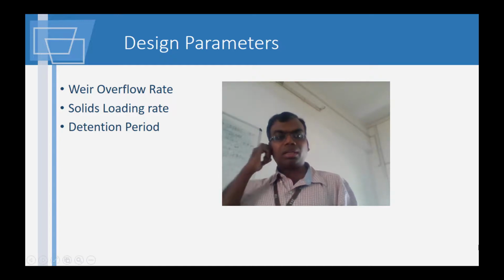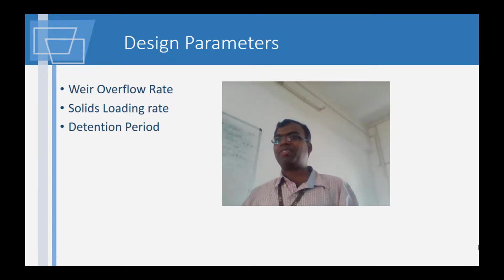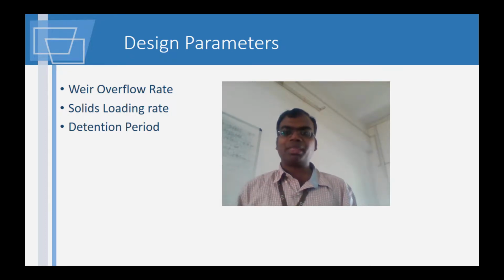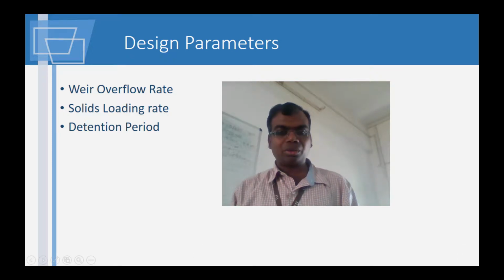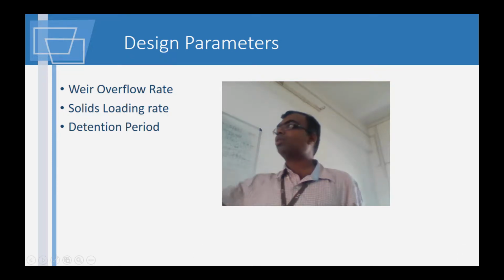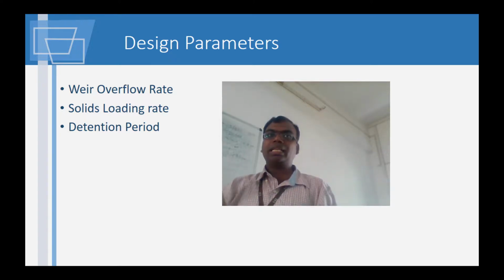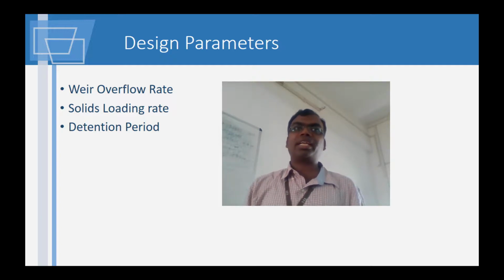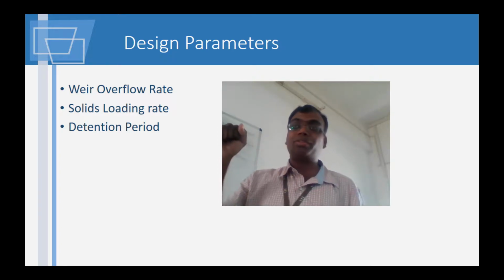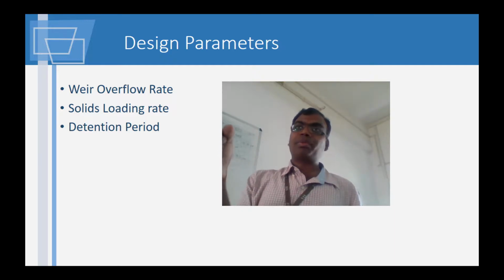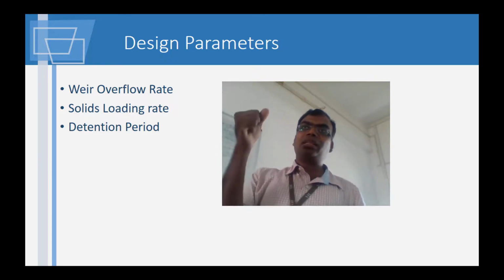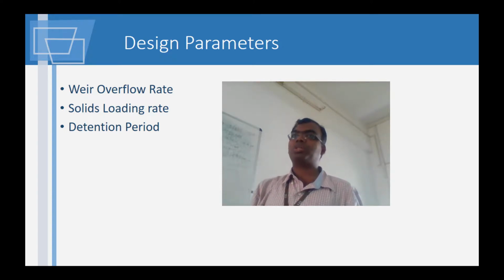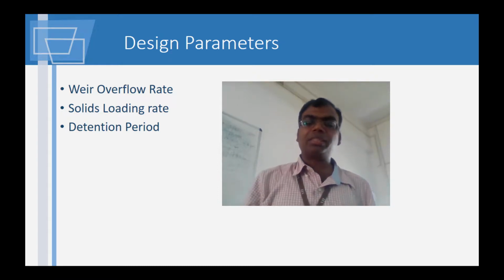The actual design parameters are there in the video at the end, what I was talking about. It's a very clear video of all the design parameters, and I'm going to go in for some of the sludge drying techniques. The underflow which goes out is called sludge. It will be a slimy mass, clay-like in nature, and it's very difficult to dry. You will find it very difficult to squeeze water out of a clay sample. The reason is the water is held in place because of intermolecular forces also. So you'll see some of the ways sludge is being dried.